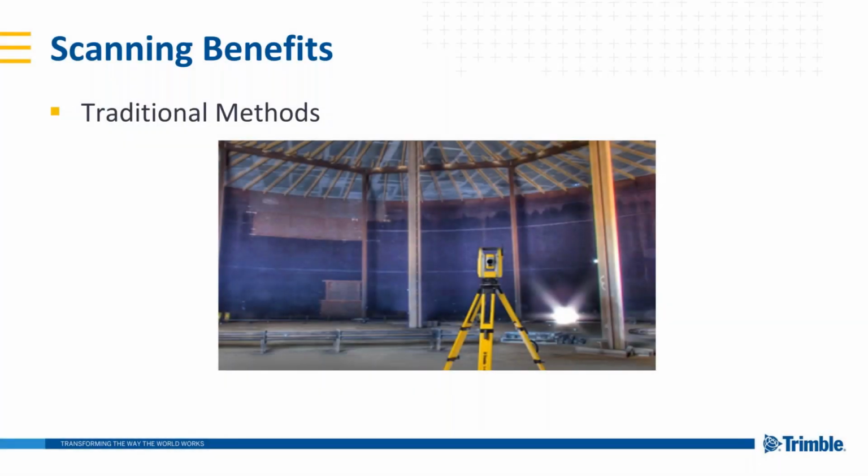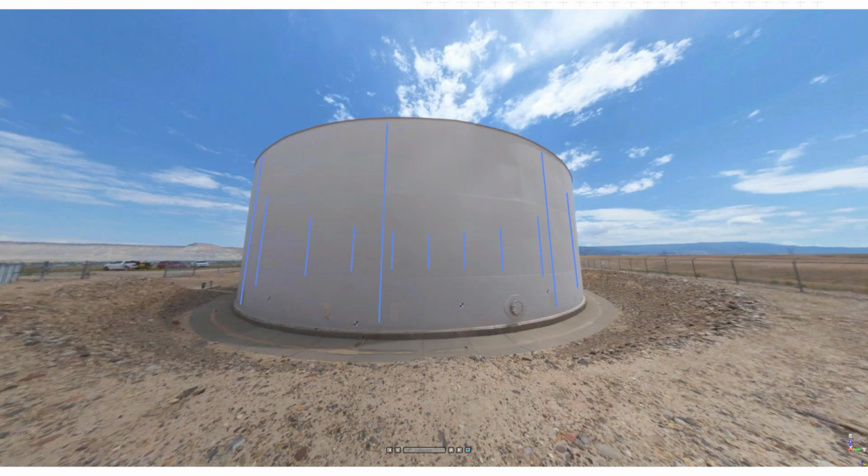Now, to compare that to traditional methods, say a total station, where you'd set up and take individual shots on the point or on the tank, such as this, you would start out with vertical inspection stations. You can think of these as mile markers or kilometer markers to let you know how far you've gone on the road. On the tank, you would start with a single vertical position, and then you would go counterclockwise or clockwise in even increments. So a small tank may have a minimum of 8. As you get larger tanks, they may go up to 10, 12, or several dozen, depending on the size of the tank or the client's request.